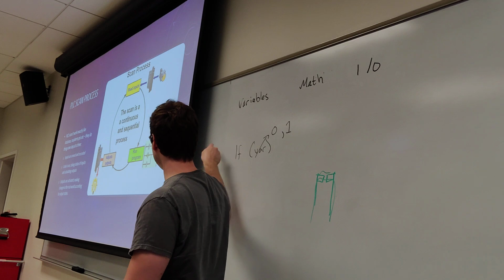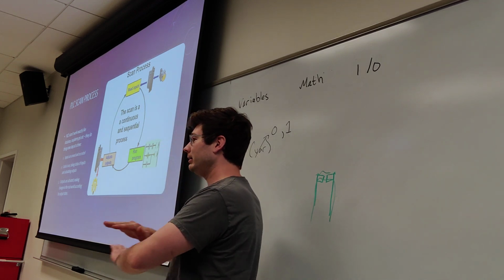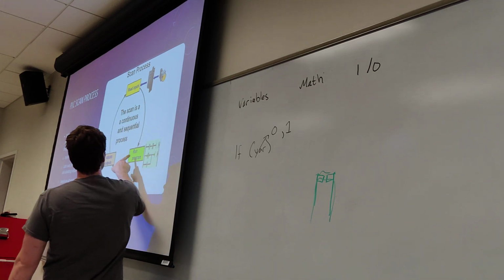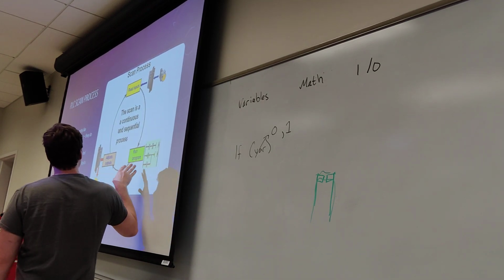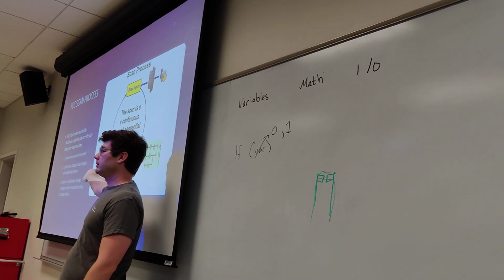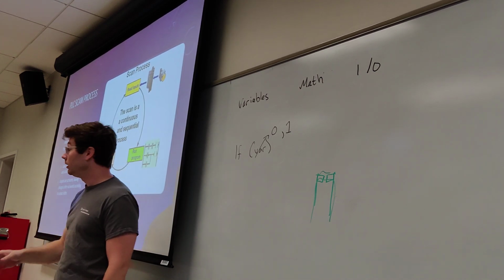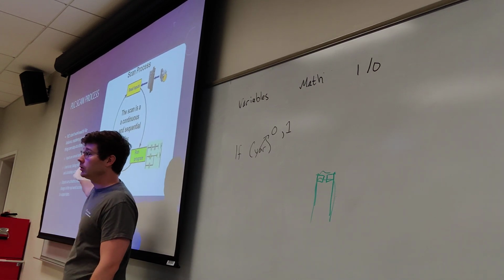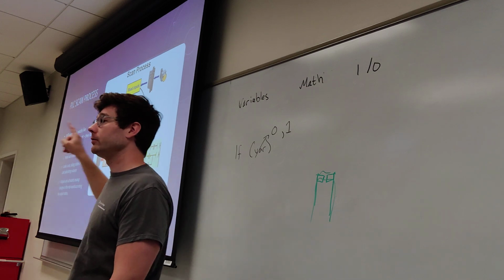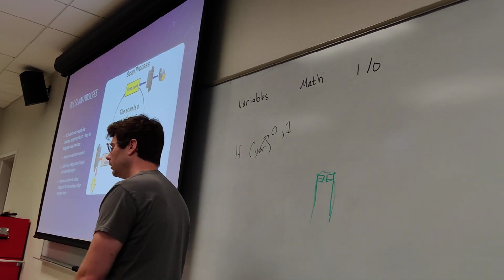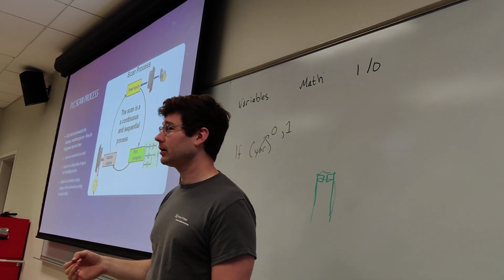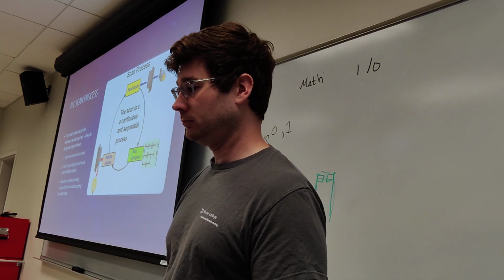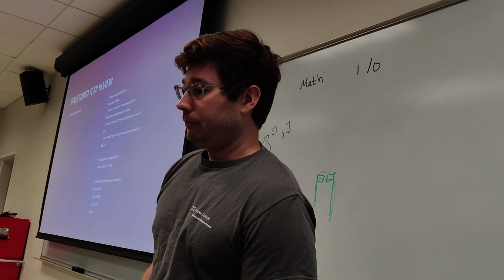It literally runs through the script, and what everything is at the end of running that process, that's what it is. That's why we do this step before the outputs, because we need to evaluate what those outputs should be at that given time. At this slice of time, our inputs were this, so our output should be this. This is the scan process that happens at whatever rate we've defined: 2 times a second, 10 times a second, or 100 times a second. The PLC scan process.